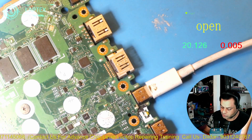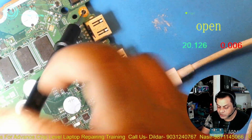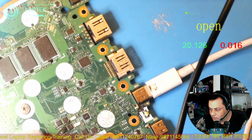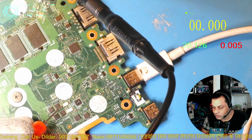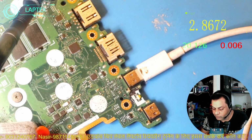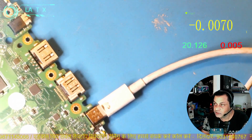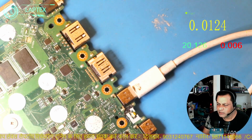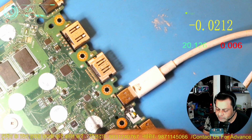As you start checking voltages, you will find something very strange that may be very useful for you in this video. So I'm going to check the voltage here. Pay attention to the multimeter. 19 volt is present here, and 2.8 volt on the other one. Here is one more thing I have removed. This is UT3. In the diagram, UT3 was written as 3 volt enable. At last I will jumper it if required.